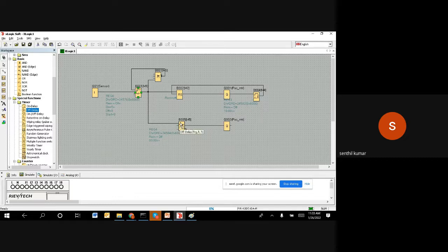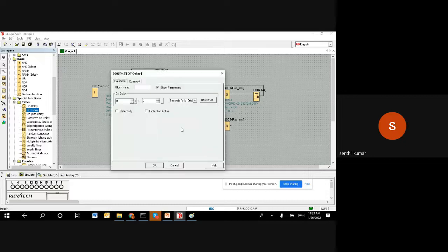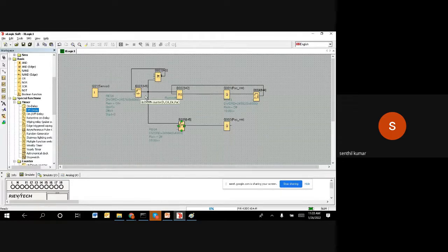It goes via the off delay timer. The output becomes on immediately. Then immediately what will happen? This goes on, it will become a reset. It will become a 0. This goes to 0. But since it is an off delay timer, we configured this as a 5-second delay, though the counter output becomes off, this conveyor runs for 5 seconds and then it goes off by itself, right?